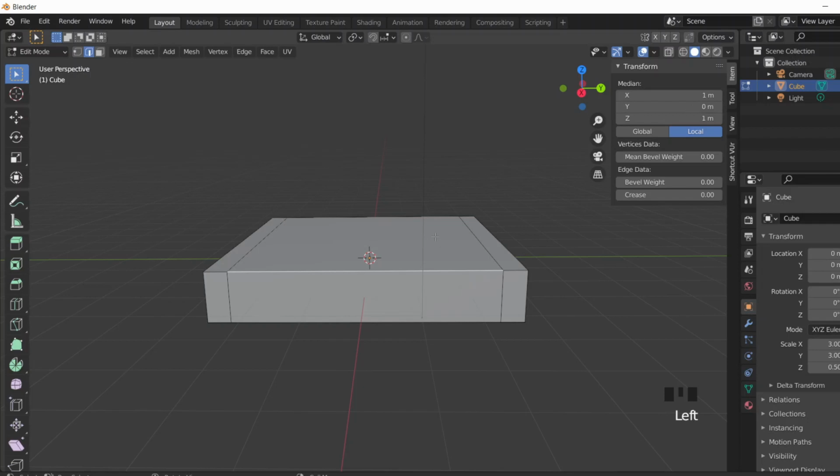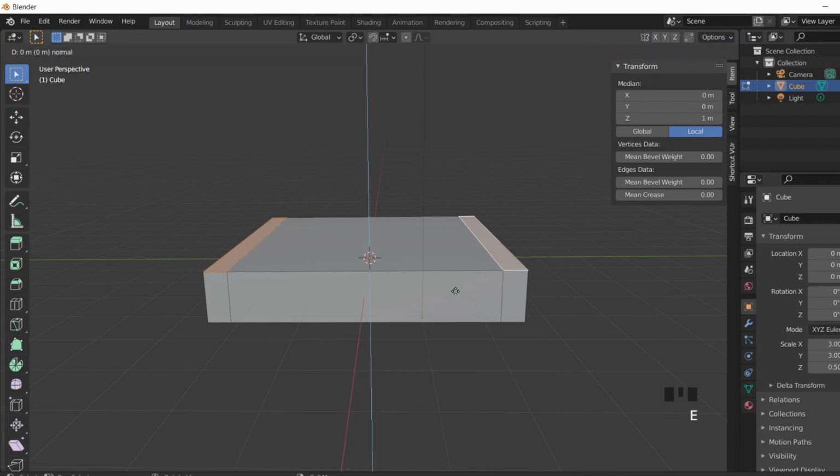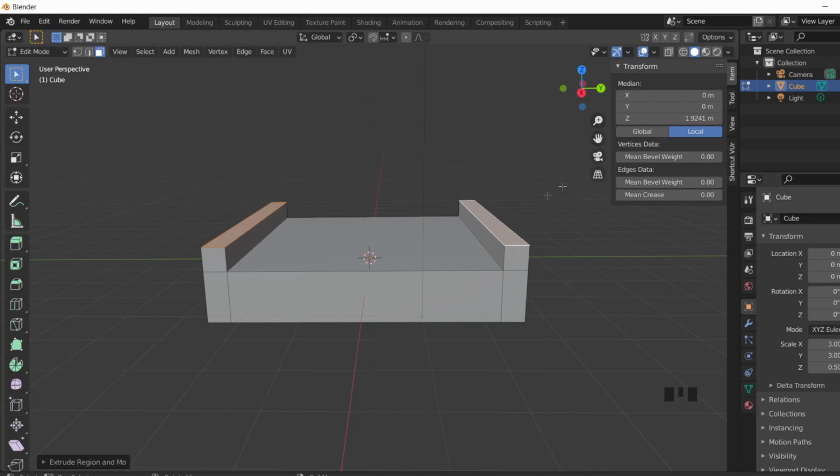So with that, we can then click on these faces. So we're going to hit 3, then shift left click to select both faces. We're going to hit E for extrude, and then we're going to constrain that to the Z-axis. So now that it's constrained to the Z-axis, we can go up and it extrudes our curves. We can also define how much it gets extruded by this section in here. So 1.5 or maybe around 2 would be better.